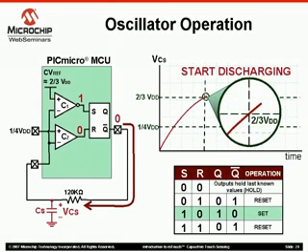Once the voltage across the sensor capacitor exceeds the internal voltage reference on the non-inverting input of comparator 1, the inverted comparator output connected to the set input goes to 1, driving the Q bar output of the SR latch to 0. The sensor capacitor then starts to discharge.